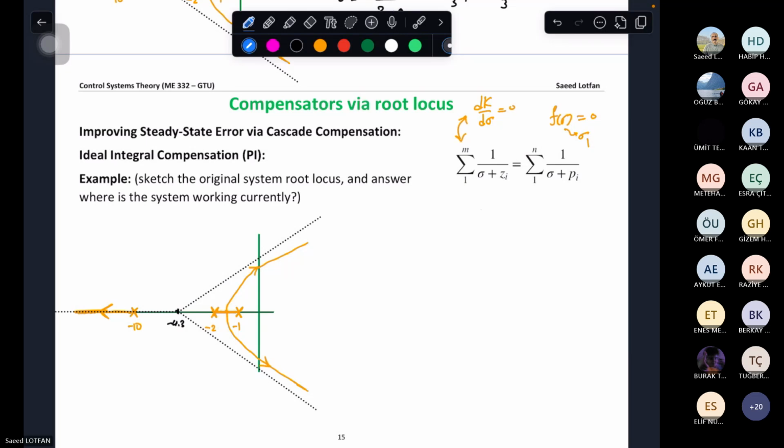First of all, I know that zeta of the system is 0.174. This means I know cosine theta is equal to zeta. So if I do that, I know that this theta here is giving me where I am, like this. So this zeta is giving me where the system is. Accordingly, we can find that the angle here is 100 degrees, and theta is about 80 degrees. Okay, now this point is my point A that I'm working on, where the system is.